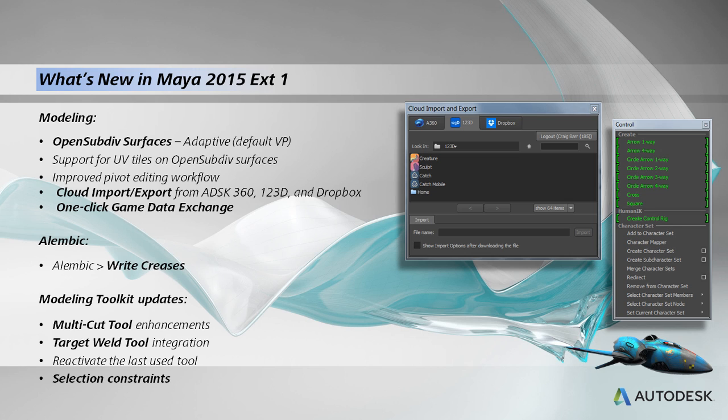So, modeling toolkit updates. We're going to really spend a lot of time in the modeling toolkit here, looking at the Multicut tool enhancements, and the Target Weld tool, which is the combination of several tools for merging components. We've combined that into one tool. Things like, in the modeling toolkit, the ability to reactivate the last used tool. So while you're working, you can quickly reactivate and switch back and forth between tools. As well, we've added the ability to utilize selection constraints based off of different surface features on a model.